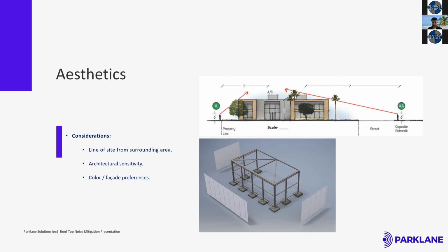You still have to get the measurements. You don't know how much to mitigate unless you know what the sound levels are at the penthouse. Otherwise it will be an iterative process, trial and error. You're just asking, is this mitigation good enough? No, it's not, then you have to go back. So it's better to involve an acoustic consultant in this instance. It doesn't take a lot, they're not that expensive, but they give you a very accurate estimate of what needs to be done. This way the mitigation can be straightforward instead of trial and error.